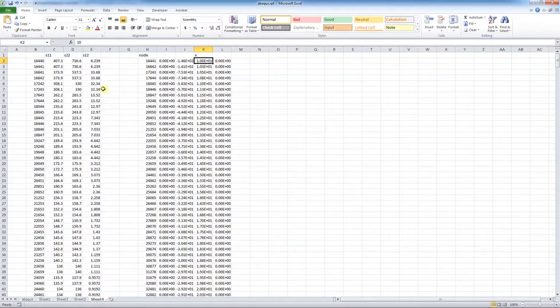And these must be elements. So this isn't exactly what we want. We want only the elements, only the nodes that are in this node set. So what I think it's done is it's gone and found some additional nodes that are not on the bottom, but they're in the element set that composed of the nodes on the bottom. So that's not quite what we want.